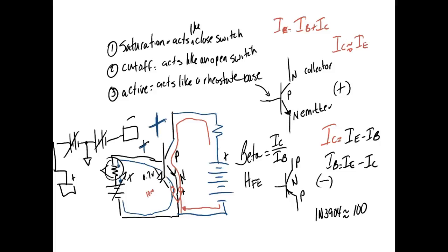Yes or no? So notice here what's common on these. Well, minus, plus are common over here. When I look down here, what's common? Minus, minus. So that means you can't use the two power supplies that are on the trainer. But what they do that for is that here I can get around 15 volts, and here I can get around 15 volts. This would be plus 15 volts, and this would be minus 15 volts.